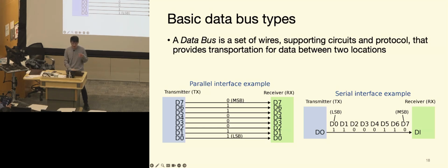So on the chip-to-chip communications, they almost always have limitations on the space. The connectors take space, and so usually on the outside, we just use serial ones with a limited number of pins. Also, chances are these things do not require super fast communications. For the on-chip ones, the reason we're able to do that is because it's so compact, and the parallel wiring inside the chip is much easier to do, because the connecting points are so much smaller.